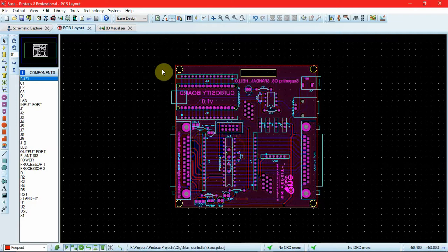This layer is necessary when the board is going to be covered by a container that will be covering a part of the PCB or similar restraints in the product. So to avoid overlapping of the parts on the circuit, we can make the keep out layer for the designer to understand that the components should be placed inside this layer.